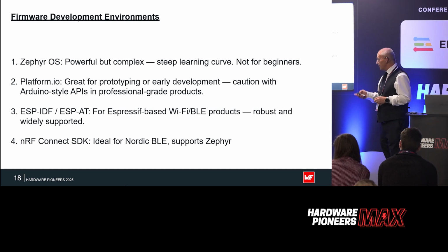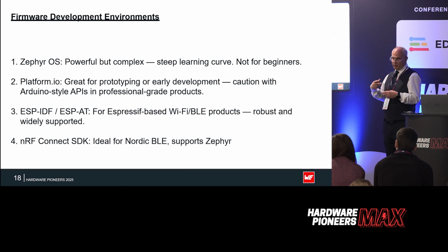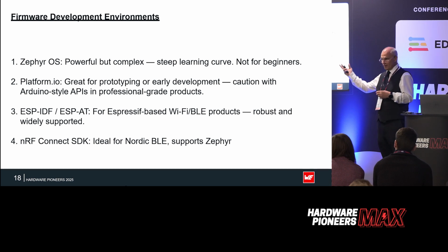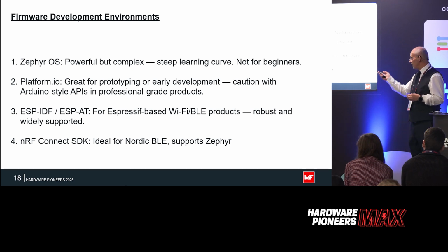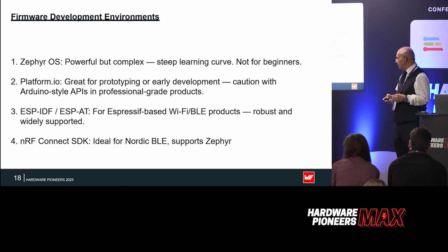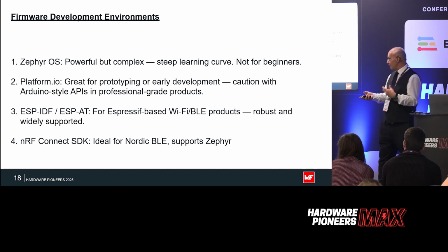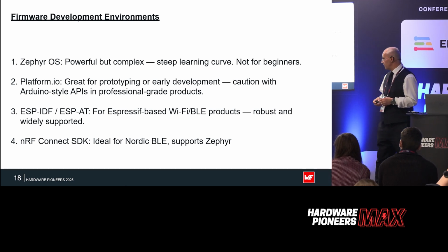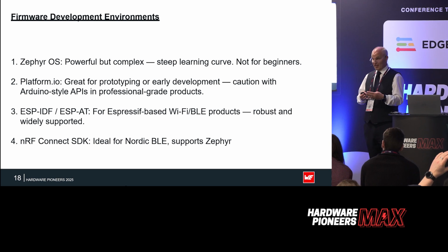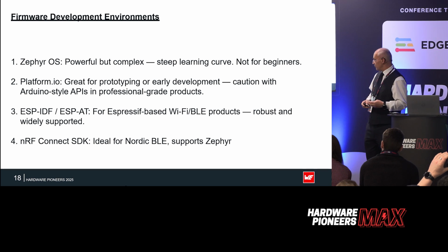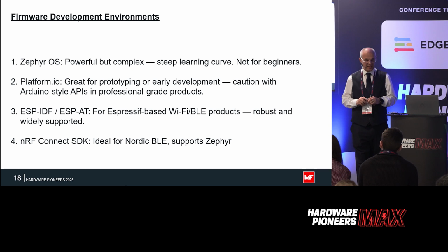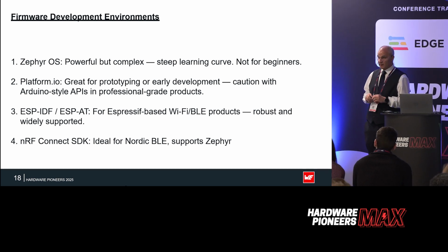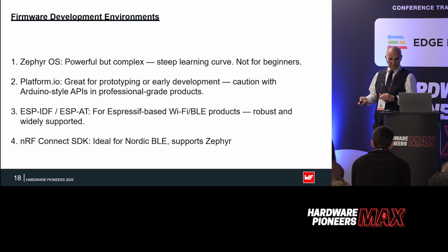We also support the Espressif IDF environment, which is a bit more professional based. So if you can move on to that one, maybe a better choice, and that also supports Zephyr as well. The Nordic chipset that we use, the nRF52840, is really good for Bluetooth and also Zigbee. The web SDK from Nordic does have really great examples on how to get that working on our devices. So really good support from those guys.